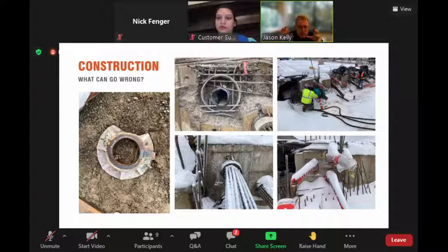And it doesn't really have any condition issues, but traffic backs up every night, people going home from Vancouver. And why? Because it's only 3 lanes and it doesn't have any shoulders. So it's functionally obsolete because it doesn't have enough lanes because more cars use it than it was designed for. And 2, it doesn't have shoulders. So if a car breaks down, it can't pull off to the side and let people pass. It's stuck there. There's no shoulders. So it's got functional problems. And that's why it needs to be replaced.